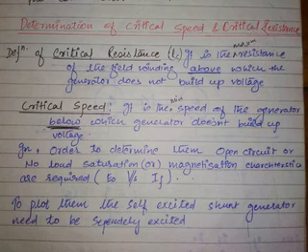You want the characteristic between E0 versus IF. If current in the field winding increases, what is increasing? Flux is increasing. If current in the field winding is increasing, flux is increasing proportionally up to saturation. After saturation, flux won't increase. Now, as IF and phi are proportional to each other, you are plotting E0 versus phi.